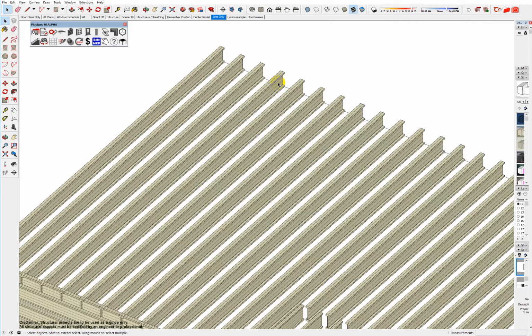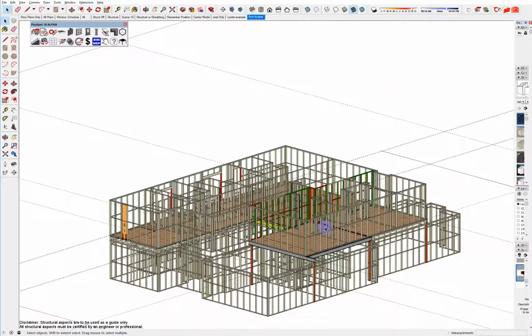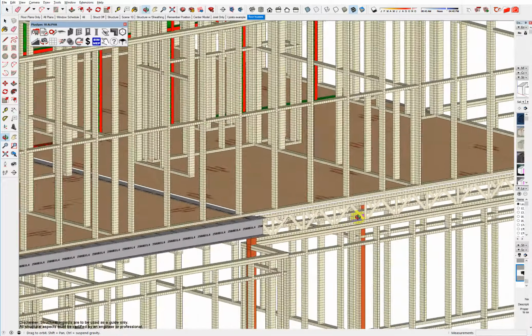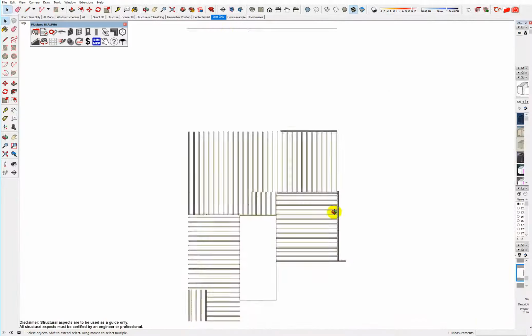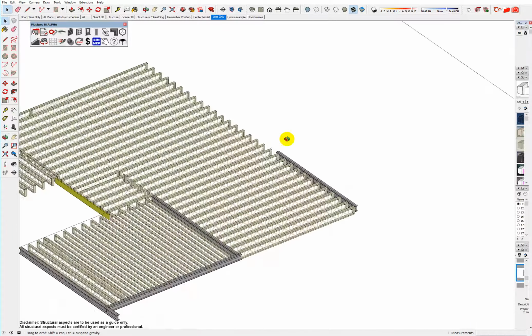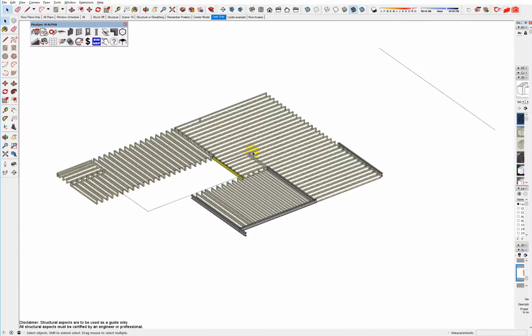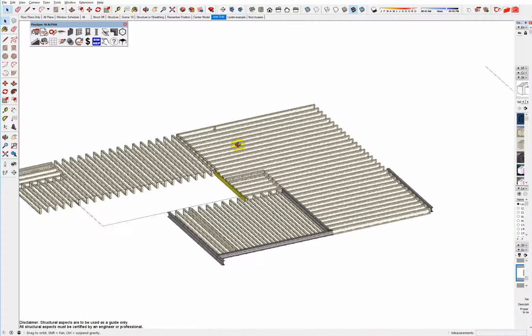However, I could also be using floor trusses. So if I was going to look at, say, floor trusses in that model, I would want to understand exactly where they have to go and how they actually work in conjunction with steel. I also want to understand what the cost difference is between the two, and I also want to know if I could use offcuts in different areas, and obviously with truss joists we can't do that. So there are advantages with using I-joists, and there are advantages with using truss joists because we can run ducting, pipes, a whole heap of MEP through these joists.